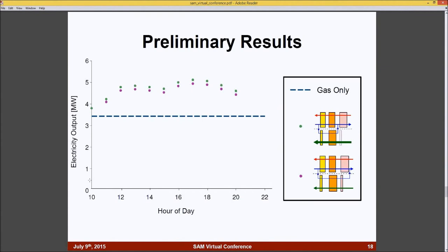And here's a little bit of physical interpretation, just to see that it makes sense. This is applying the proxy model that we've just created over a surface. You can see that the region where the inlet solar field temperature, on the bottom axis, exceeds the exiting temperature, on the y-axis, is infeasible. We also put an extra constraint saying that the exit temperature has to be 30 degrees higher than the inlet temperature. The behavior is what you would expect: as that temperature differential gets low, the mass flow rate gets a lot higher.